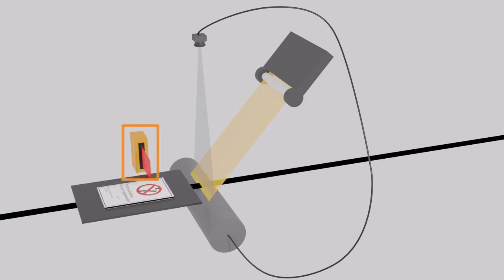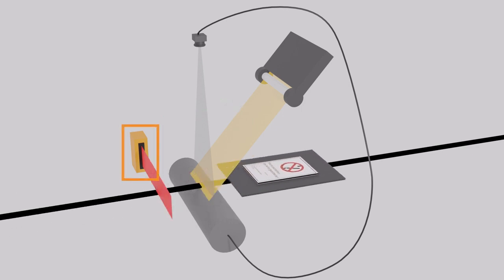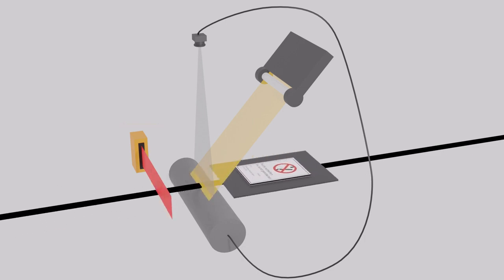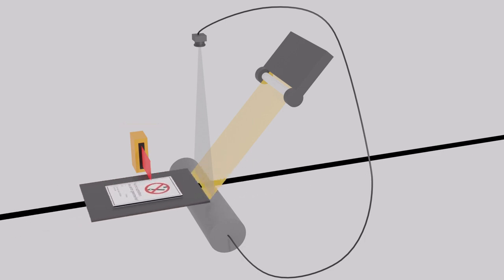The photoelectric sensor is needed to trigger the frame start, when exactly the camera should start to acquire lines. In other words, it ensures that the camera is capturing an image while the object is passing under it.